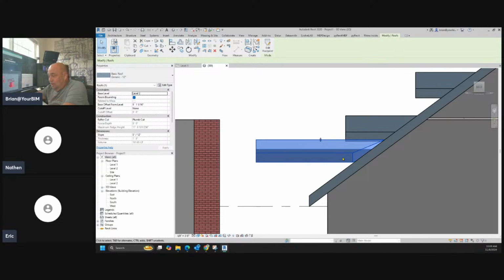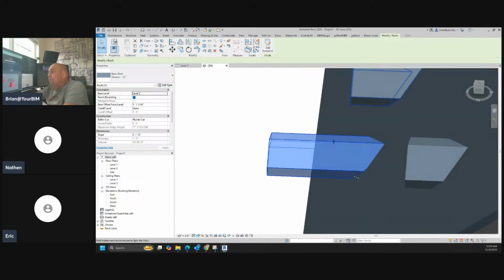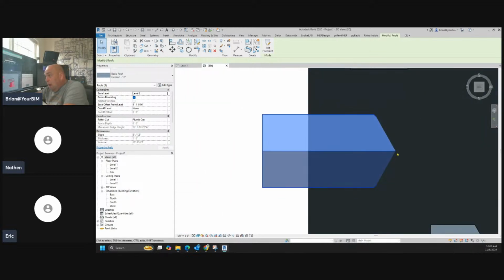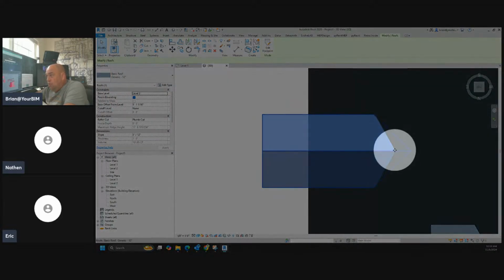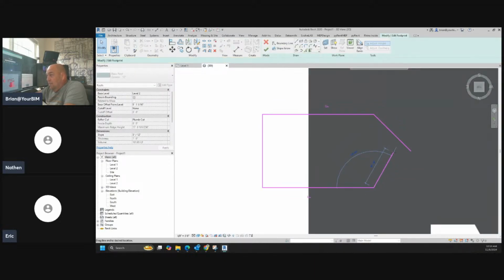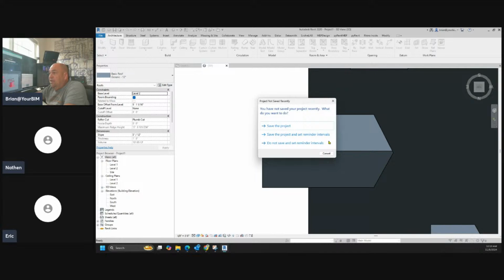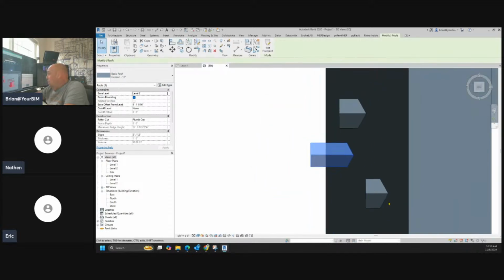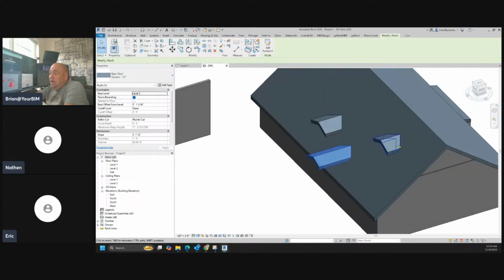And then I would go through all this geometric nonsense to figure out, where does that actually hit? See, so you can see I'm just doing this approximately right now, but you have to do the math to make this stuff exact. If you really want a correct model, when I look at this from the top view, I would need to figure out where that exact point was right there. Because you see where my point is way inside there. So I would need to take this, and then I'd come out here something like this and something like this, and it wouldn't be exact. And anytime I change the pitch, as opposed to the ones that are automatically attached, you see they recalculated all that on their own. Yeah, it's just less work, quicker.